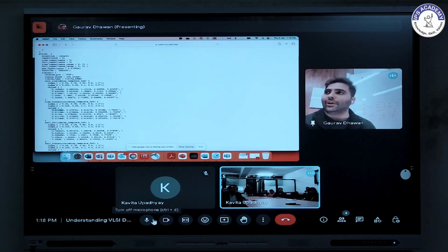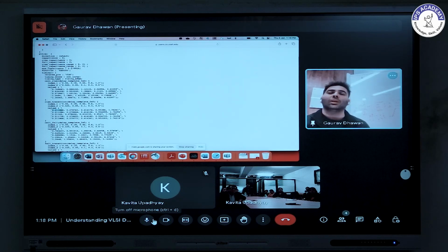Yes, that's a good point. This data, what you see here, 0.06 nanosecond, will be given by the design team, because the design team has already designed this circuit under a certain set of conditions. They already know under what slew conditions this design is intended to work. They will know that this design should not work beyond 1.2 or 1.5 nanosecond, or even if it works, there's no guarantee. They have tested this design only under this range, so they will give you a range.